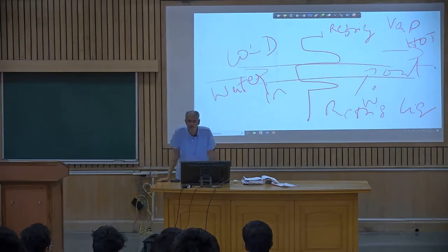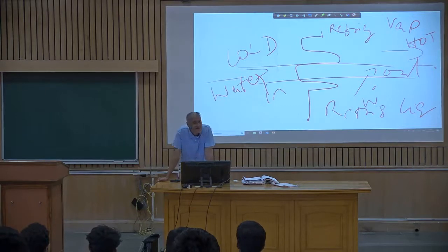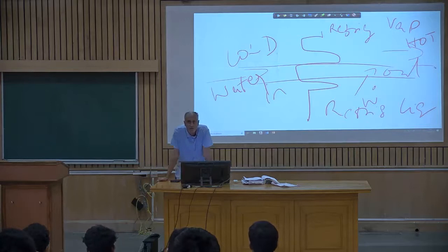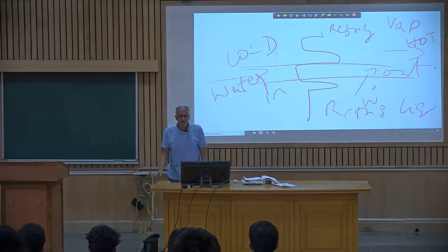So since you said viscous, these are extremely viscous. These are high molecular weight materials. So the only way to make them flow uniformly with a good amount of velocity is to pinch them, squeeze them. How do you squeeze them? Send them through a nozzle. So one small caution you should use, the area change should be gradual. If you keep it sudden, what will happen?